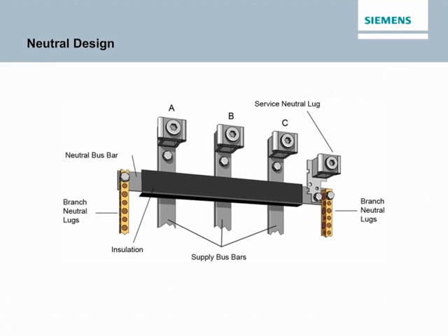Siemens lighting panels feature a split neutral design, which means that neutral connections are available on both sides of the panelboard. Split neutrals are connected by means of an insulated neutral bus bar. Some loads can cause harmonics and non-linear loading on a distribution system. This requires special consideration when ordering a panelboard. One way to deal with non-linear loads is to double the capacity of the panelboard neutral. A 200% neutral is an available option on Siemens panelboards.